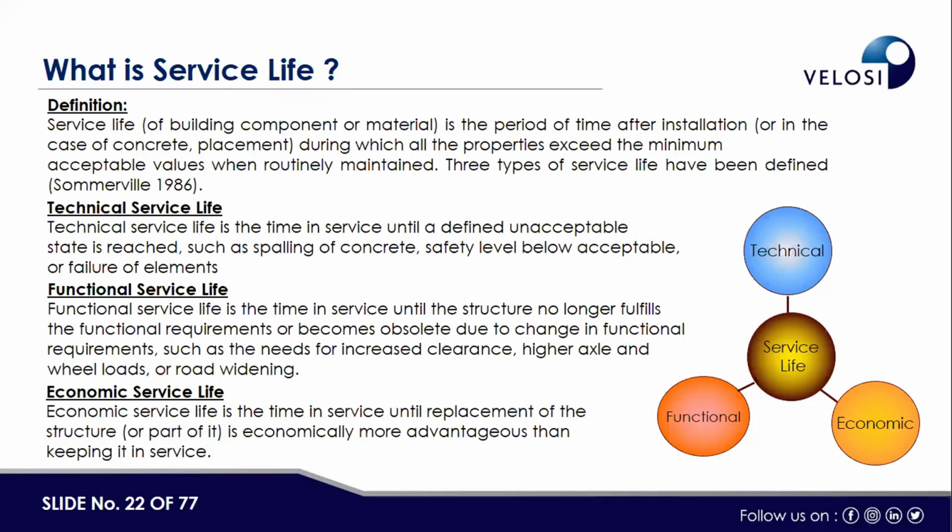Technical service life is the same as we normally design: when the building would be able to serve its life as it was technically accepted. Functional service life applies if the functional expectations or functional load of the building or machine change. What would be the next life expectancy from the same building or machine? Similarly, economic service life is a question of when it is economically viable. For example, if repair, replacement or refurbishment costs become more than the advantage or revenue from the normal operation of a building or equipment, then it's better to replace. Otherwise, you can extend the life by doing the required refurbishment activities.